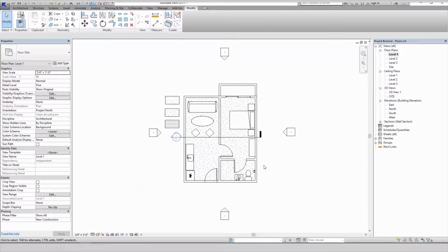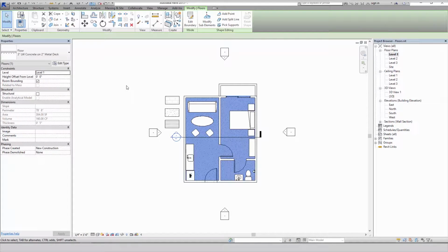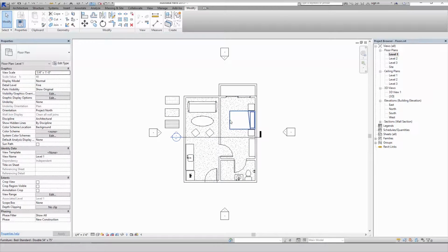So now, when an interior designer models the flooring, you'll be adding onto the floor the architect has already placed. But to do that, you first need to recognize what exactly the architect is giving you in their model. Some architects may just have the 2x framing without the plywood layer. If that's the case, you need to add that to the properties of the floor you are creating. In our case, we can see the floor is concrete on metal decking. Therefore, we want to make a wood floor with a subfloor in the common area, a carpet and pad in the sleeping area, and a tile on thin set in the bathroom.